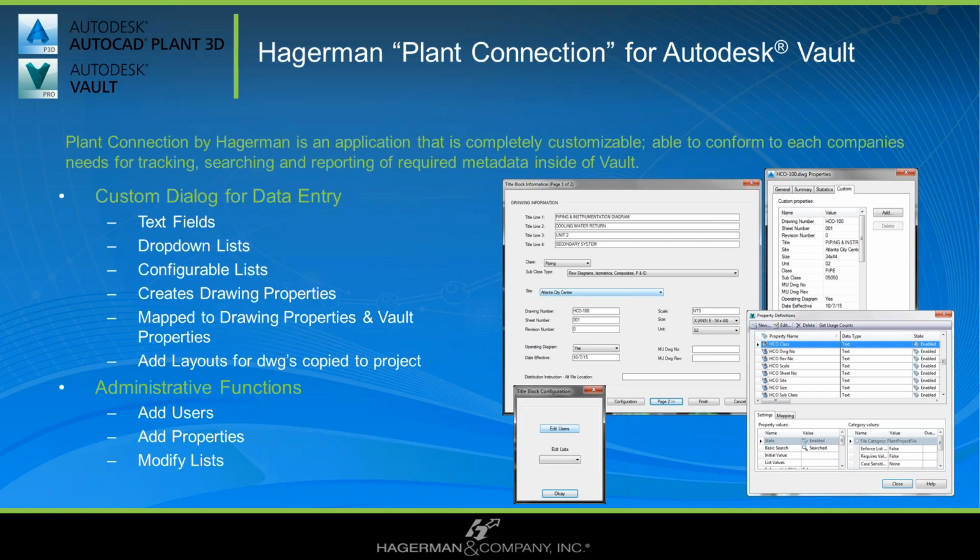So when plant and P&ID is involved, you check your drawings into the Vault, but when you do that, you're creating and checking those same drawing files along with the database and the data associated with the project files into a separate database. So it's very easy to break the link between the master database and the local workspace.